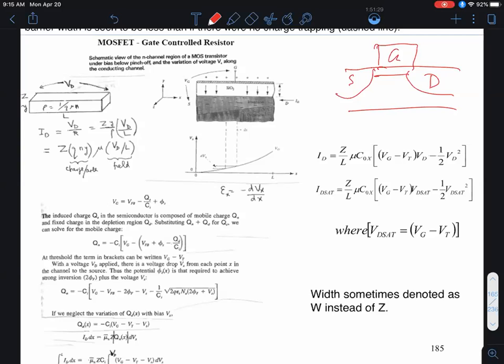All right, so we're looking at the MOSFET now, which is a three-terminal device where you have a source, drain, and gate. But as I've told you, it really has a fourth terminal, which is a substrate, okay? Now, for this MOSFET, we'll always have to reference the voltages to one terminal, and the convention is to assume that the source voltage is the ground voltage. And generally speaking, we'll also assume that the substrate is grounded, okay? Though sometimes we can apply a substrate bias, and that gives rise to this dependence of threshold voltage on substrate bias, as we mentioned last week, okay?